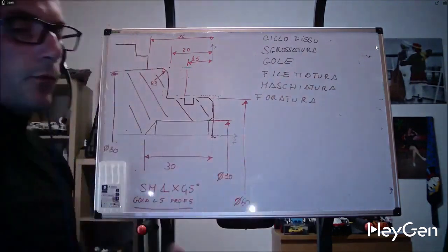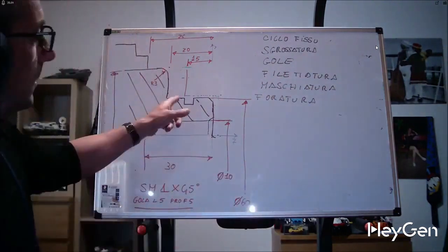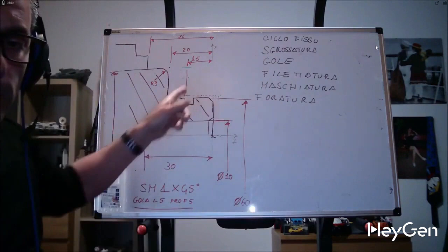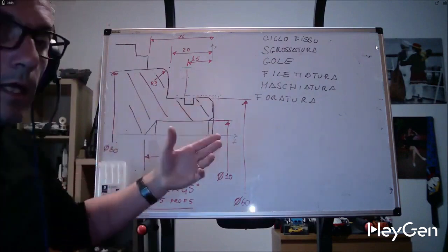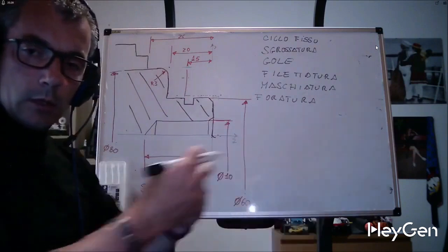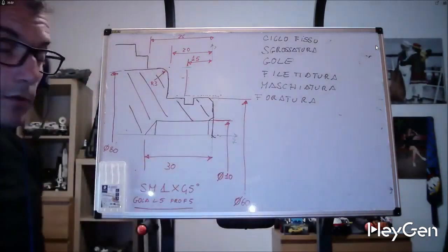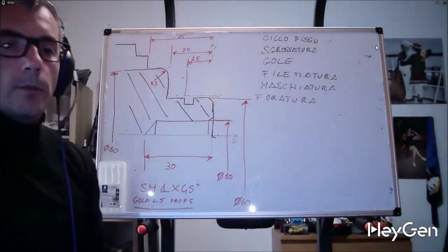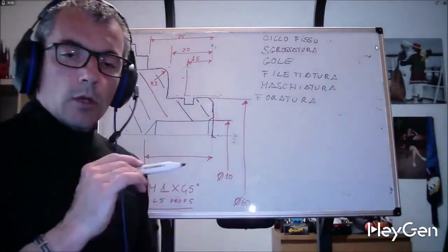Also, these fixed cycles for threading, once you provide the length, pitch, diameters, and depth of cut, will handle the back and forth for you. Tapping cannot be programmed.